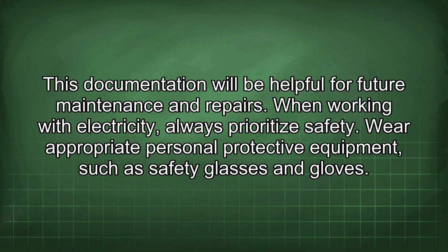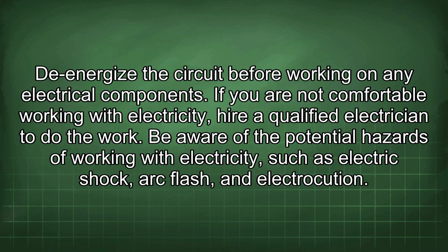When working with electricity, always prioritize safety. Wear appropriate personal protective equipment, such as safety glasses and gloves. De-energize the circuit before working on any electrical components. If you are not comfortable working with electricity, hire a qualified electrician to do the work.